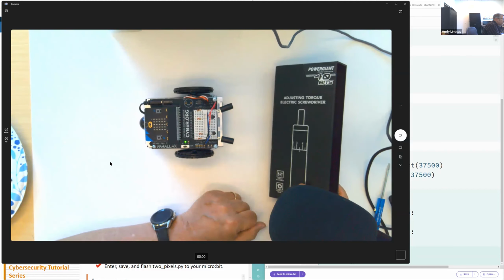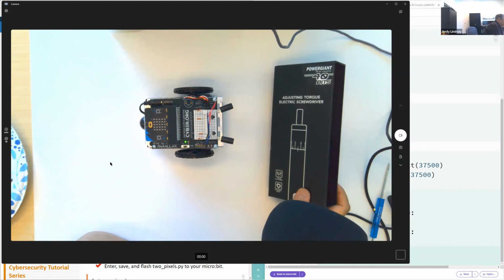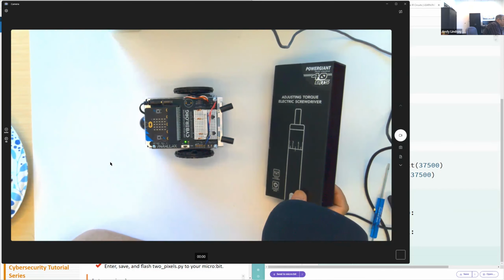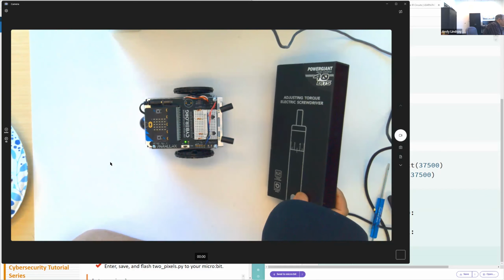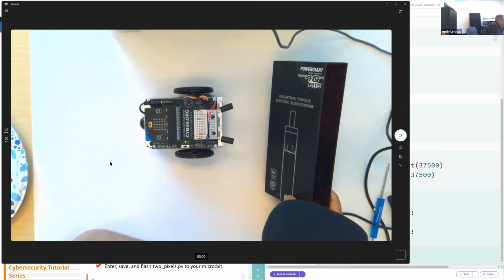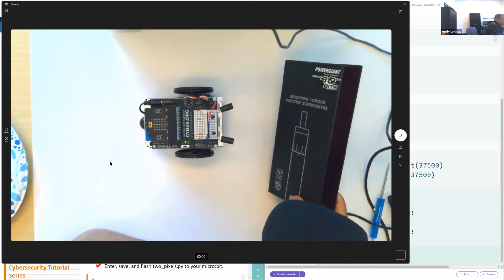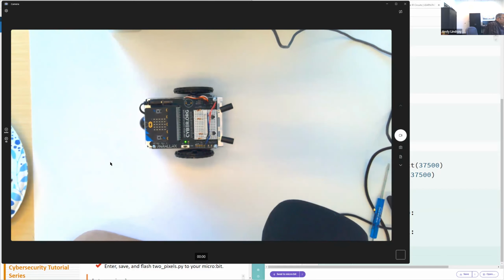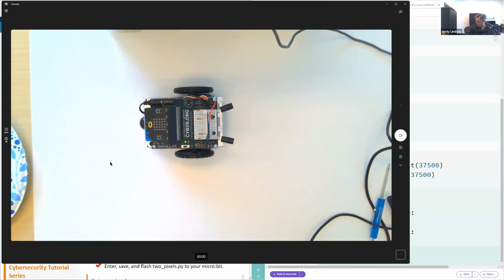And so this is suspect because instead of reflecting infrared light, it might just absorb it. It might actually reflect it quite well. It really depends, but usually stuff like electrical tape and cove base, those kind of black things absorb the infrared light. So they're not good objects.